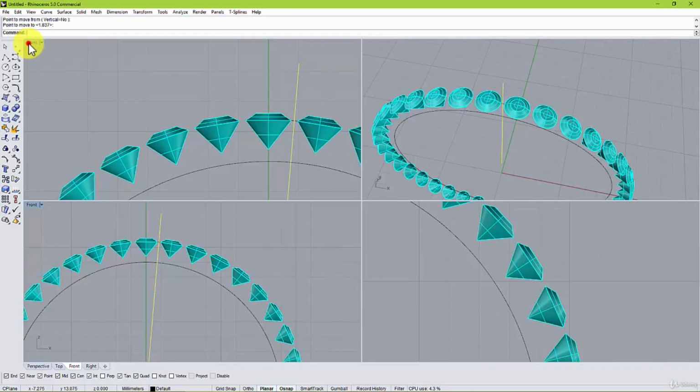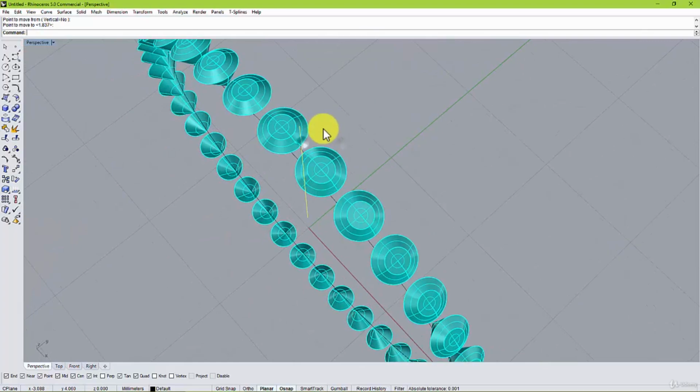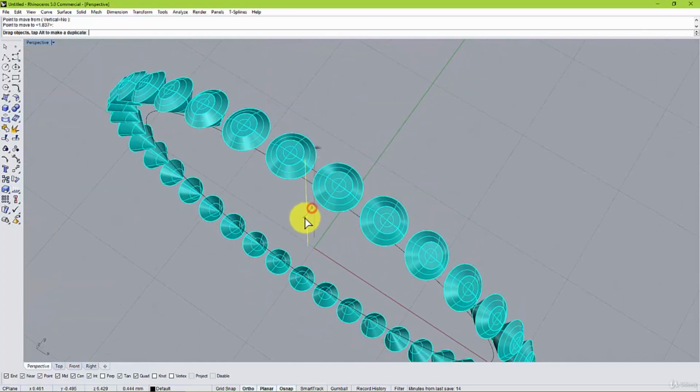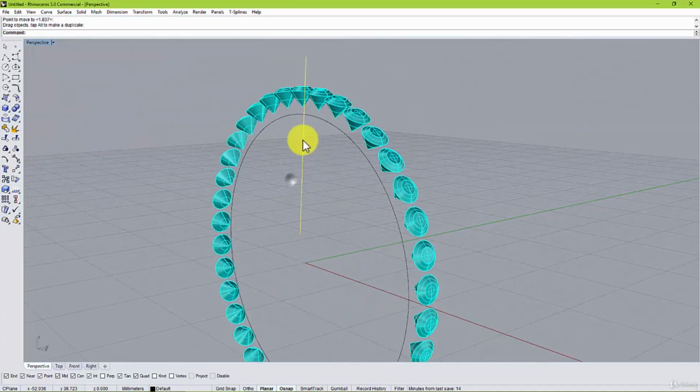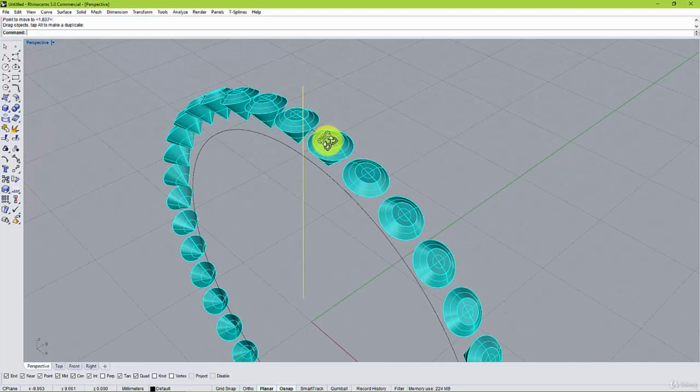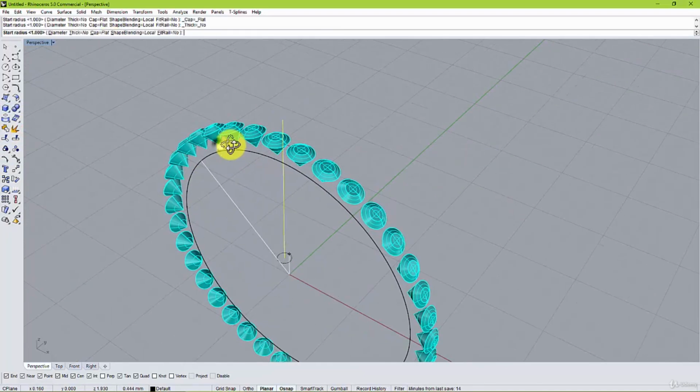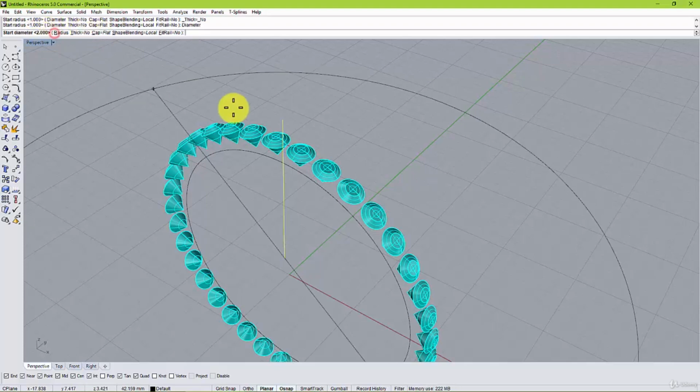Now I'm going to make one of the claws to see if it's thick enough. I'm going to make a pipe. It's also here on the solids menu. Put it here, pipe. Thick, no, not radius, diameter.